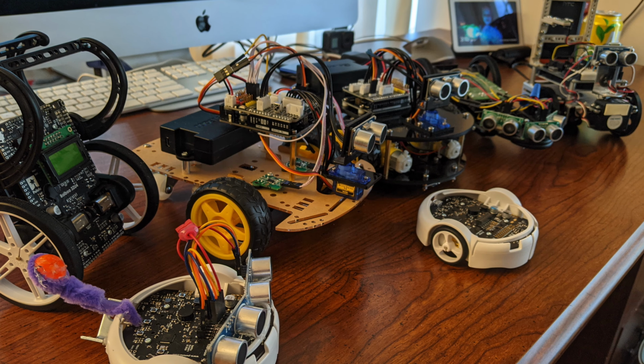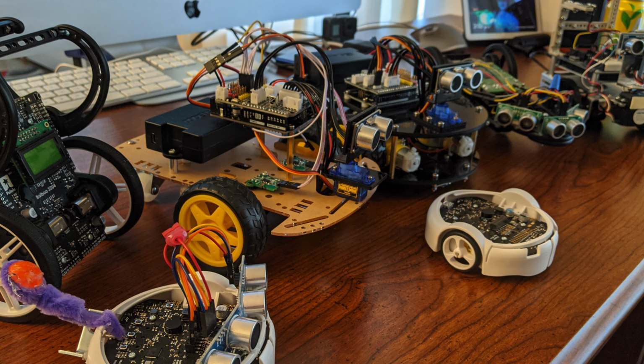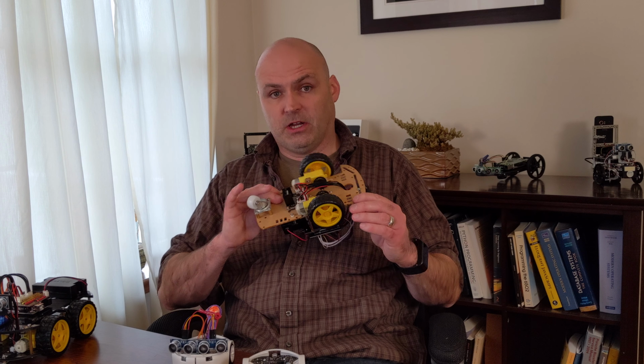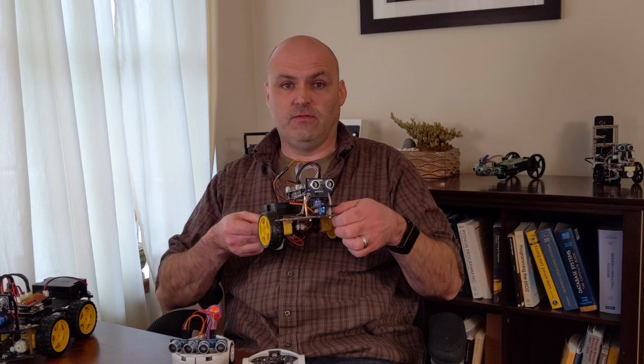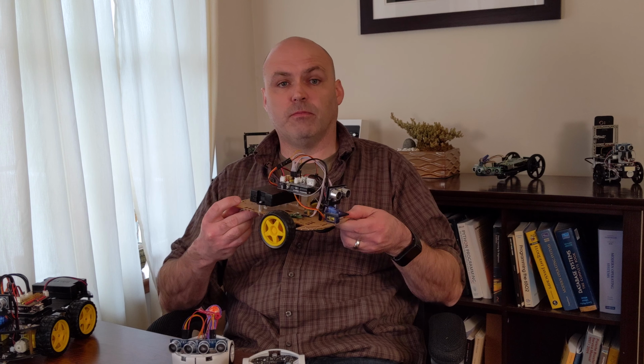I want to take a moment to look at some of the various robots here that I have in front of me and use them to help describe what we're trying to achieve with our mobile robot and what we're looking for in a good robot design. These robots here are all holonomic robots, which means that they can achieve turning to any angle at any given moment. So if you think about a modern car, if you have to parallel park, it takes multiple steps to do that. You have to pull up next to the car that you want to park behind, and then you have to cut your wheels and back in, and then if you did it really well, you can do it in a third step where you just kind of even out and pull forward, but maybe you had a few more shifts in between.